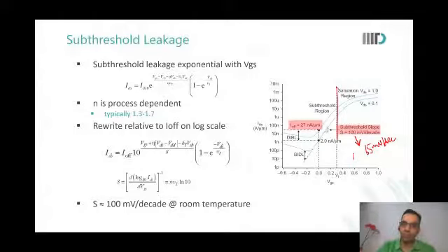Just a very small doubt. When we were discussing the MOS capacitance, the first time you told us about subthreshold, you were saying that there is a depletion width under the gate, and then there is a depletion of the PN junctions of the source and drain. So somehow they get connected, and that is basically providing a path. So that is the path for this subthreshold leakage. I just wanted to confirm.